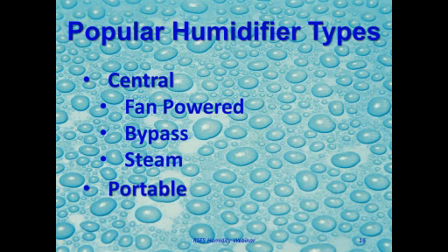With regard to central humidifiers, one of the things that a person should really think about is, do they want their humidifier to have a pan with a float that actually has a water reservoir, so there's always standing water inside the humidifier, just like with a portable humidifier, because that's going to require lots of maintenance on the part of the homeowner or the maintenance people at the building.